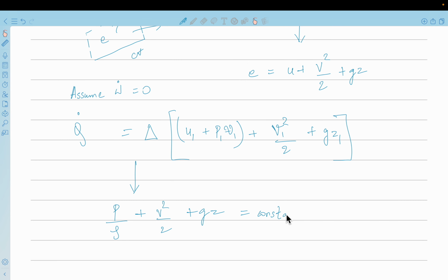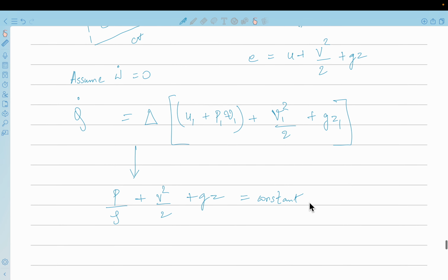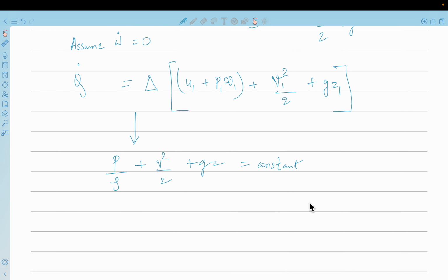Now, why I wanted to discuss this is, I'm not going through the entire derivation itself, but the energy equation reduces to this only if we have either assumed that Q dot is 0 and the U term, the internal energy term, disappears, or you assume this Q dot balances your delta U term. Okay. So with all these assumptions, we come to the Bernoulli's equation.